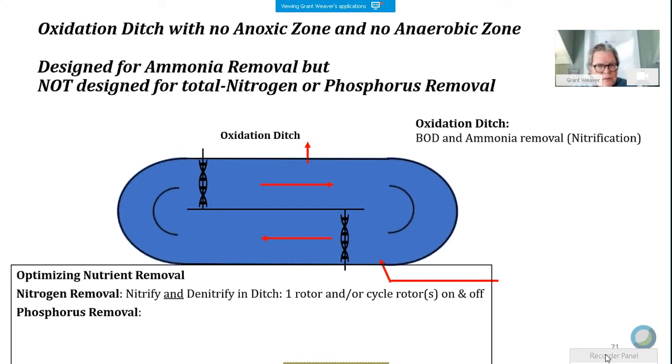For phosphorus removal, there are again two strategies. One is to actually purposefully create dead zones. I've advocated, with tongue in cheek, throwing old wrecked cars into an oxidation ditch so that you've got a place in there that's just a dead zone, and all the sludge will settle inside. Take the windows out and throw the car in, and let the sludge settle in the driver's seat there. I'm kind of half serious about that. Maybe somebody will pick me up on that.